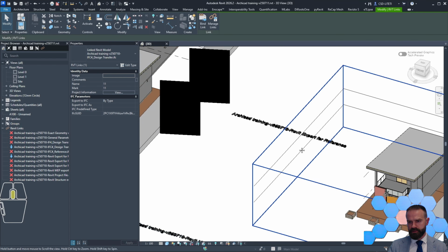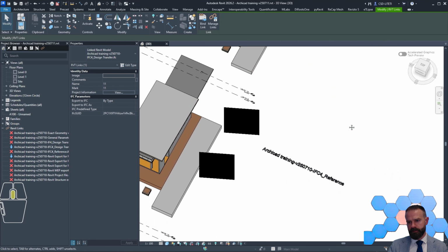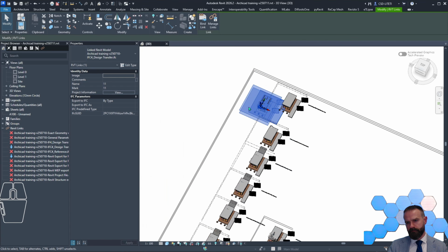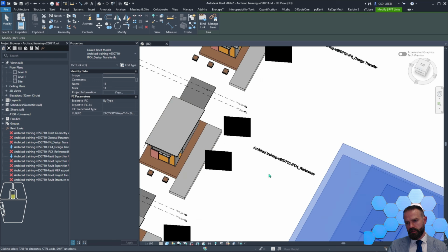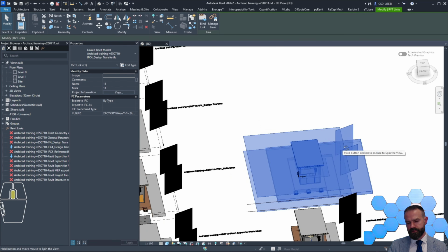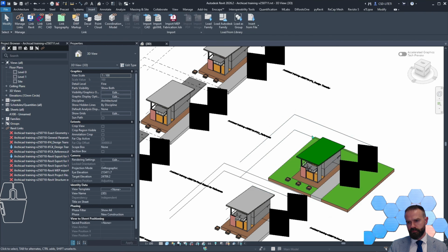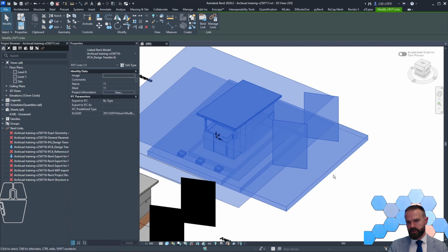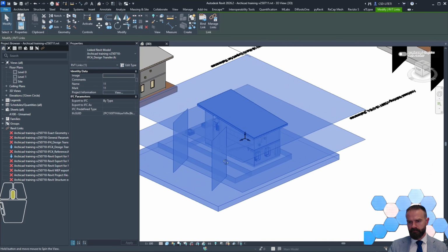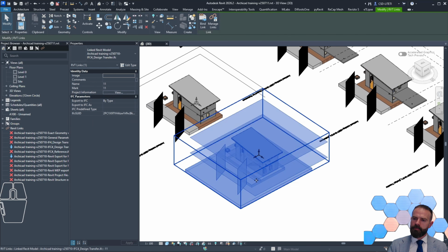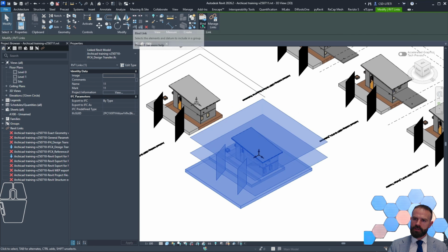So I can bring this model to a dedicated location with the IFC design transfer option, and I can bring it here. So this option works very nice with IFC4, compared with other techniques. So here I have the file which was transformed, and now let's check how the bind link will work.